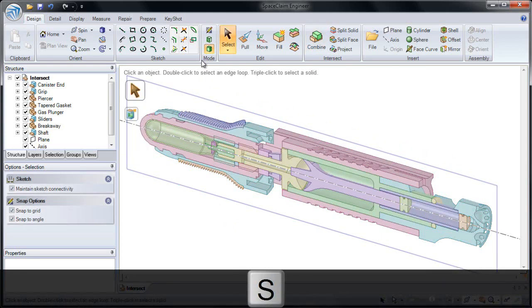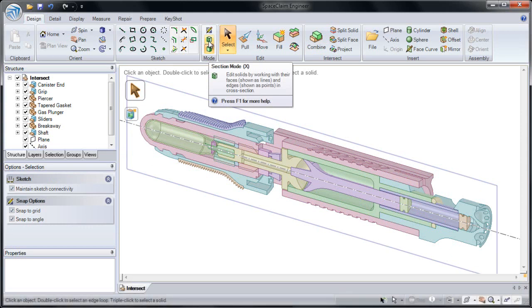And just as a note, this is different than a cross-section. A cross-section visually lets you see the section and see inside of a part, whereas by cutting the model in half, I've actually removed everything on one half of our model. So take some time to place a plane in the model and try to cut all of the solids at the same time and then remove them with a box select.